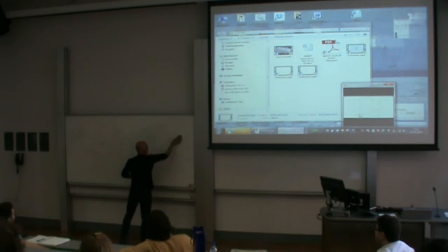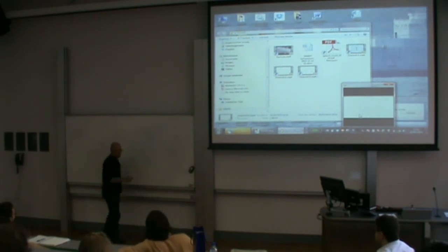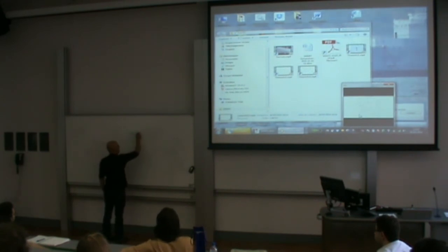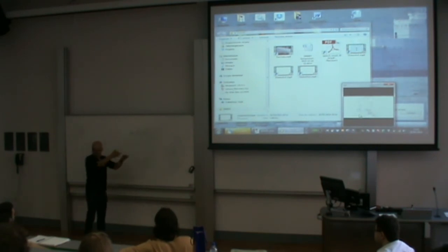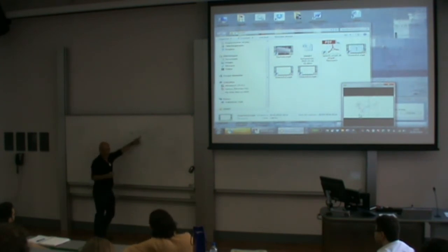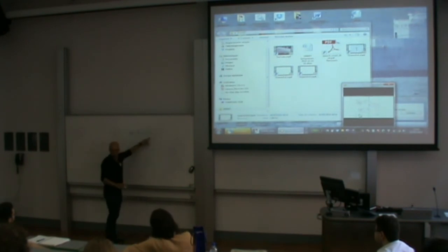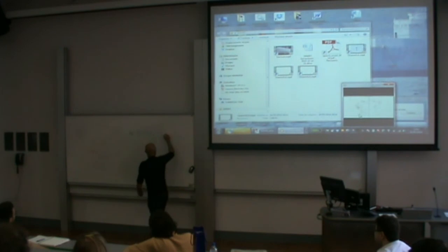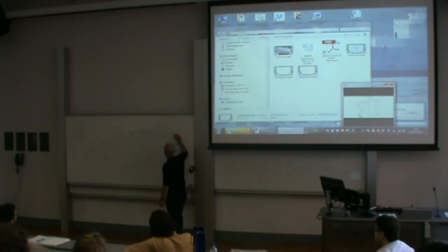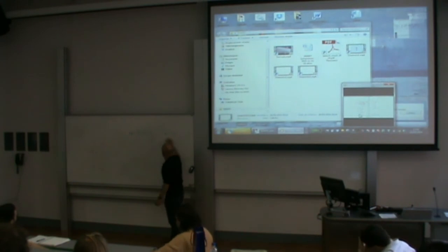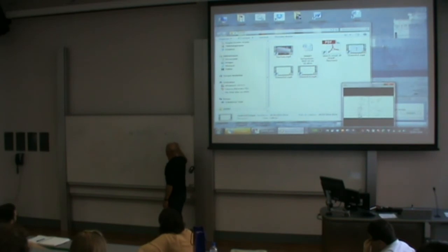First of all, my robots are assumed to satisfy a differential equation like this: x dot equals f of x and u. So what can be done if I use what I have explained here? I will use this differential equation to predict, plus and minus. I will know u with a given accuracy, it's a tube. I have some information on x, for instance the initial condition, some information on b, and some information on z.